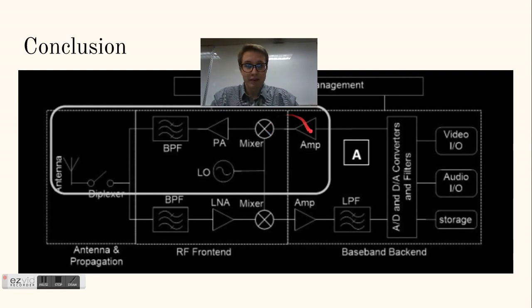So that generally concludes what we have here. We have a voice or some input going in here. It's a very low amplitude, so it needs to be amplified so the rest of the circuit can read it. Makes it more readable for the circuit mainly. Then the mixer shifts the frequency so we can use a smaller antenna. Then a power amplifier amplifies the signal to drive the current through the antenna.